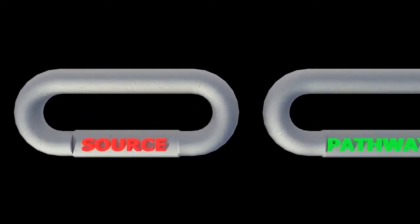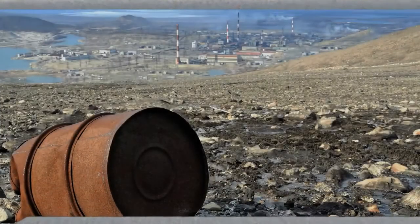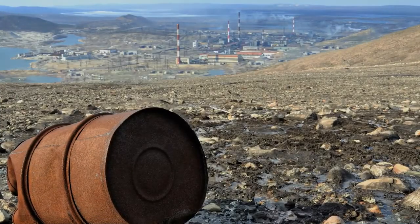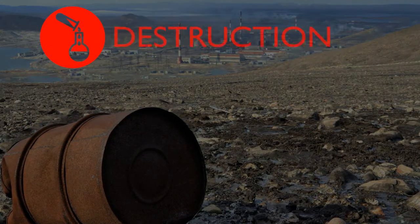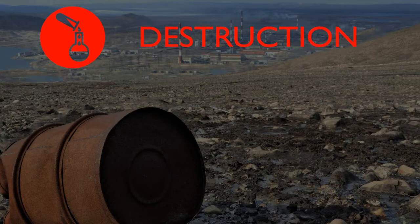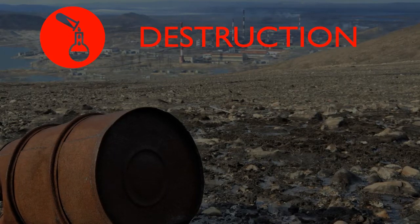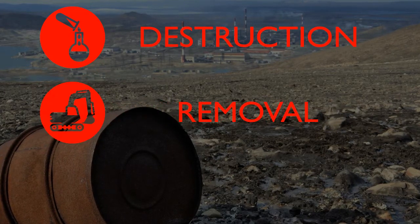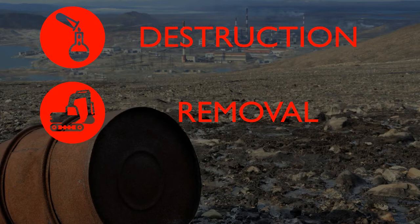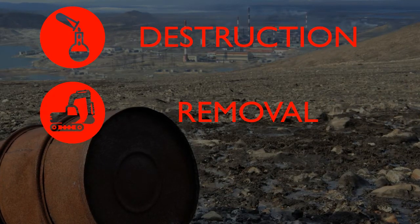Let's take the source. Source treatment involves taking action to break the linkage at source, the actual pollutant itself. In very simple terms, this involves achieving one or more of the following outcomes. Destruction or neutralisation, whereby the pollutant is rendered harmless through the use of some form of treatment, such as adding a degrading chemical agent or a process such as heat. Removal, which can entail either removal of the polluted soil and disposing of it off-site, or extracting the pollutant from the soil.